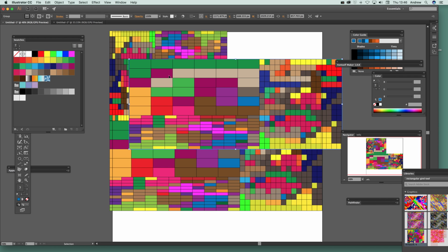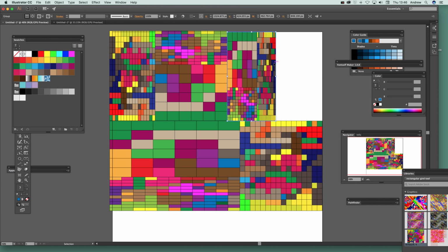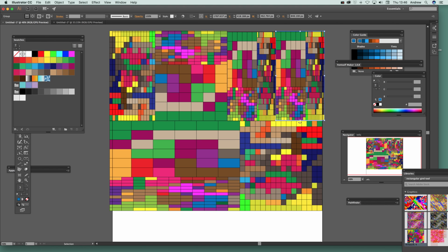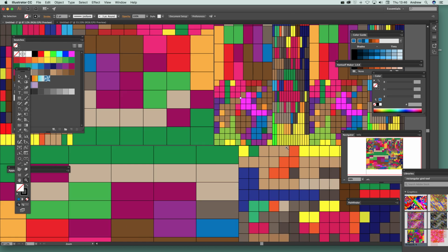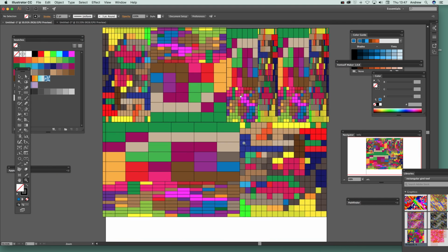And you can, of course, once you've actually created 4 or 5 of these grids, combine multiple grids together. So you don't have to use the same grid, which sometimes can end up with a sort of uniformity in the design. So it's actually nice just to be able to do that, hold again Alt, see what I mean about having a gap. There's a little gap there. And the easiest way, of course, is to quickly zoom in, just make certain you haven't. And it's amazing, every time you do it, you still find there's a gap later. So you really have to check to make certain there isn't.